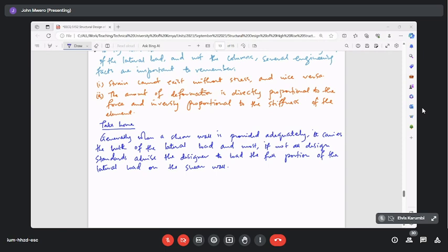So if you're doing a manual calculation, a manual design check, or manual analysis of a building that has shear walls, you would load the rest of the vertical elements with gravity loads. So you will check the columns and beams to carry dead and live loads, the vertical gravity loads.